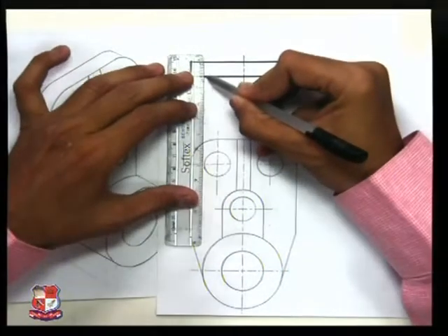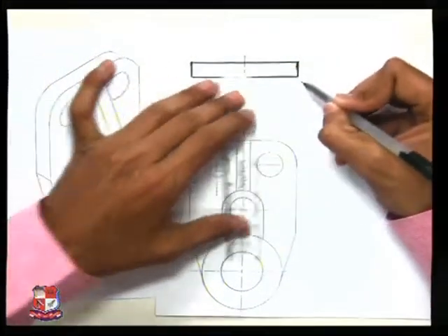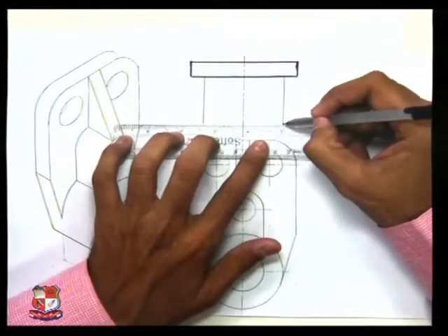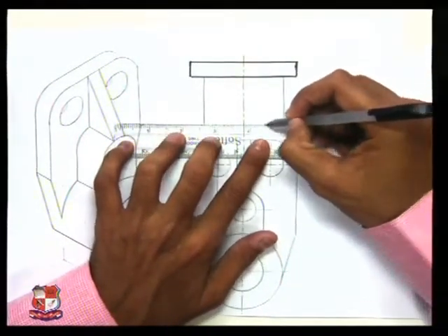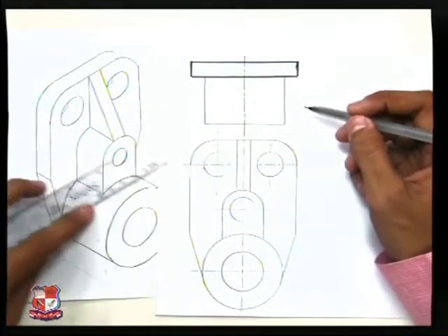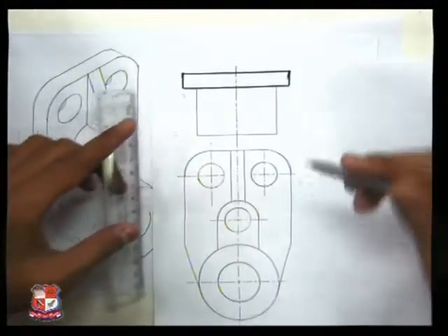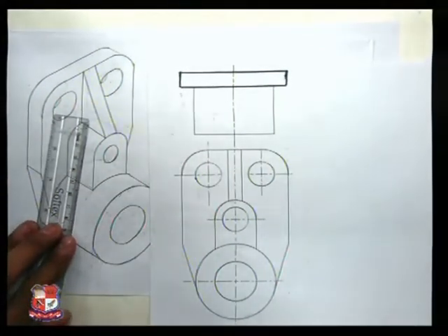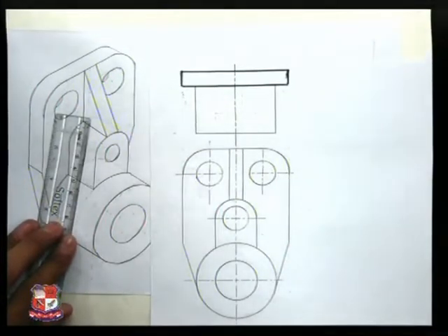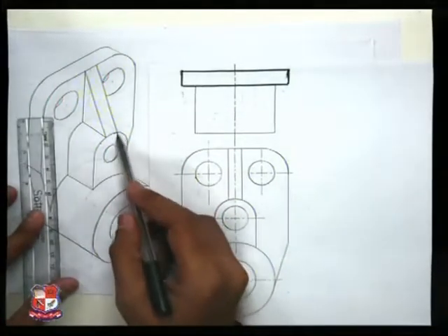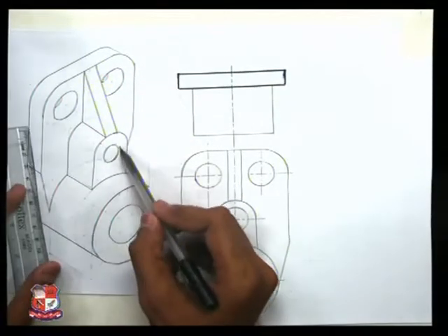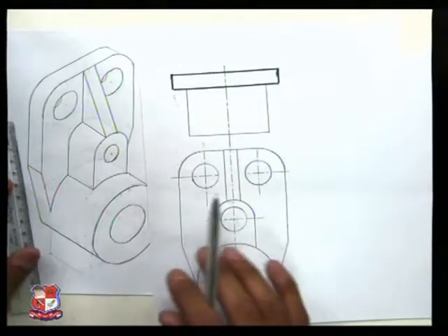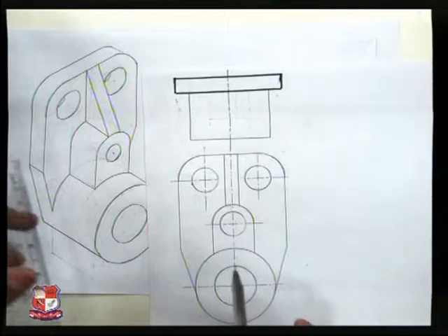So according to that given dimension, diameter of the cylinder, that is 60 millimeter given, and height from a base to end, that is 50 millimeter. So it would appear like this. This represents this cylinder, the outside line of this cylinder. Now think about this upper portion, this strip. We know this distance from center line, this center to this, is equal to the radius, and the radius is given in the figure, that is 15 millimeter.